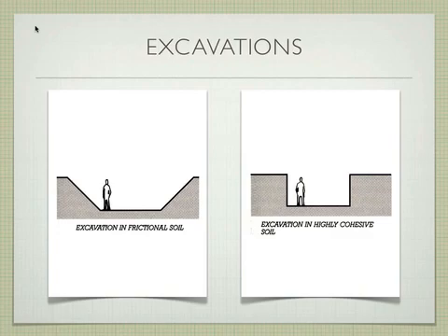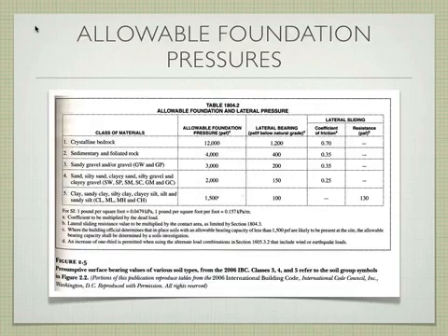But if you're in some kind of very cohesive soil, gravel, clay, you can dig this almost straight down on the sides, and it's not going to collapse in on the side. So it depends on the effort required to dig, depending on the type of soil you have. So this would be sand. You're going to have to do this type of excavation to be able to get this whole same area clear at the bottom. So there's a lot more that needs to be excavated in this type of soil. And that's certainly something to consider when you're building.